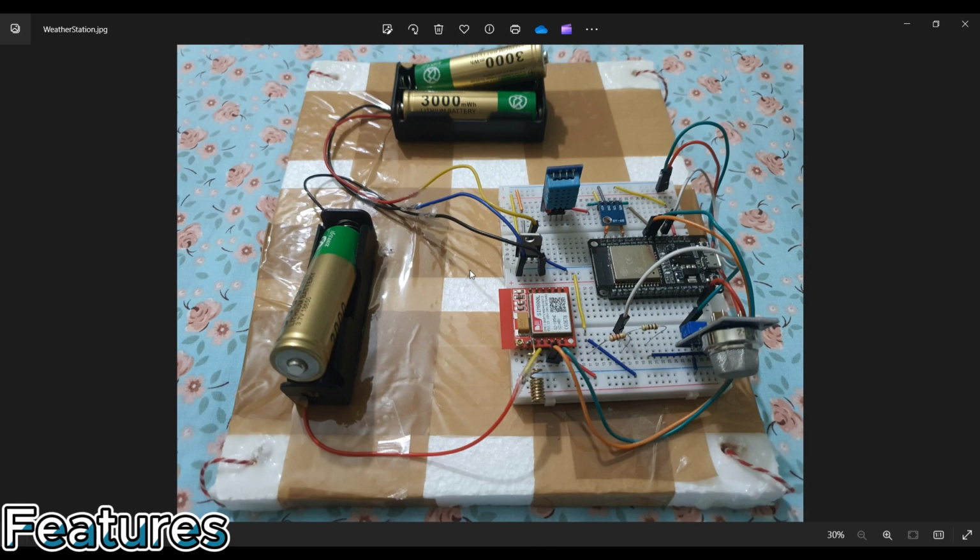So among all these, based on the availability of components and making things more compact and lightweight, which is another important part, so that the drone can fly with the least amount of thrust possible, consuming lower power, I had to go on with the first approach, that is by using the GSM module. As you can see, the SIM800L GSM module, the red one, is very compact, small in size, and very lightweight.